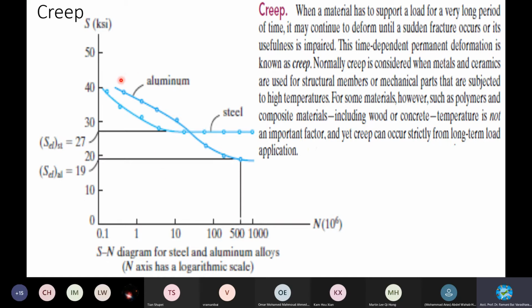And then when you come to aluminum, it starts with a good value, and then reduces to a very low value compared to the steel member, and then it just creeps or maintains a constant value, then responds or regains its original position. Just maintain. It's all happening between the ultimate and breaking point. That you have to remember. It has already reached the yielding point, started yielding, and then maintains a constant value until it breaks. At one point it will break.